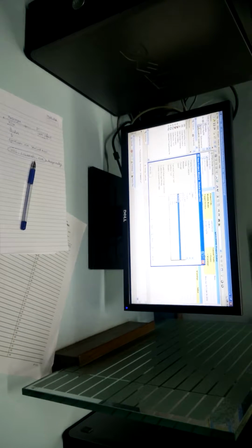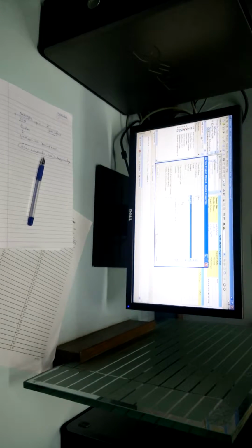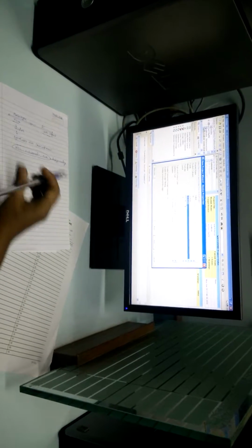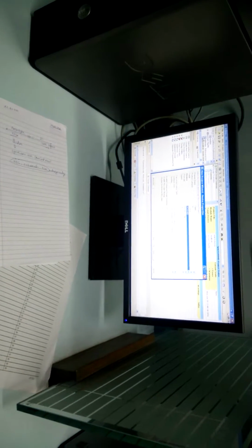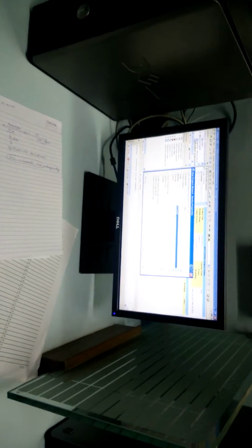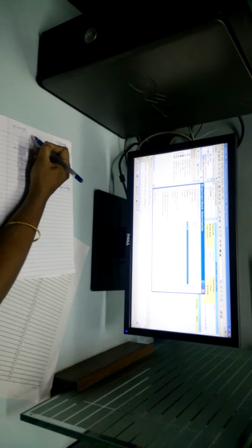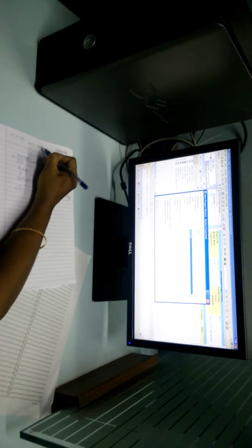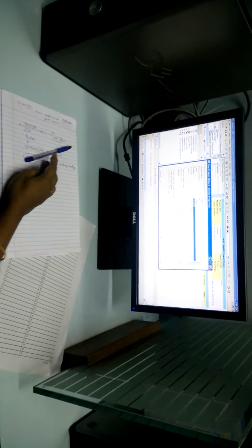Out of these members, XC3S400 is the chip or device available in our lab, so we select XC3S400. Now, what is the meaning of XC3S400? XC stands for Xilinx Corporation, 3S is Spartan 3, and 400 is the number followed by K. So 400K equivalent gate count. Now you know the meaning of the equivalent gate count of the design.